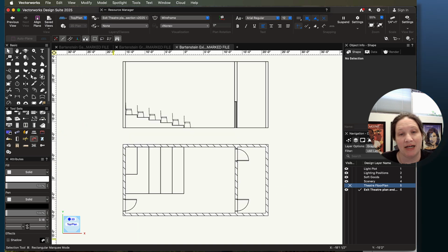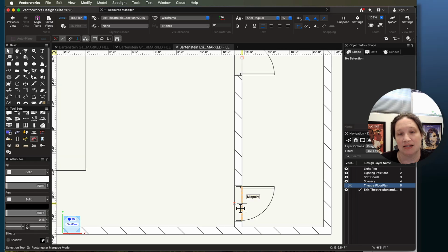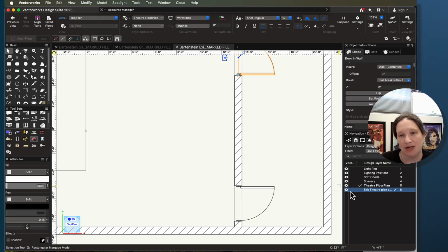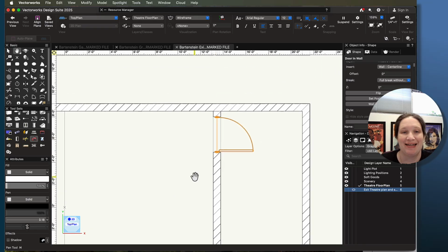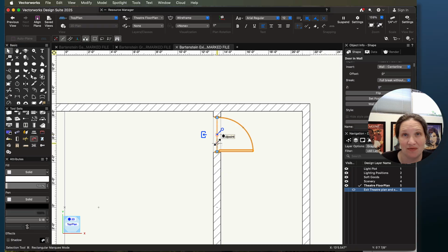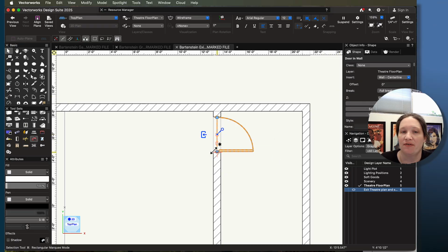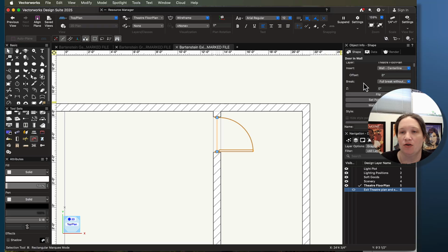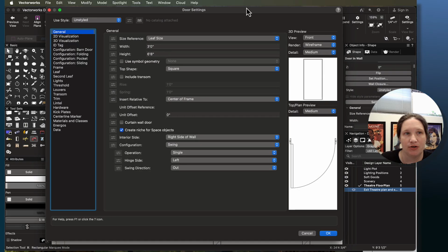In a plated version of this, you would actually not want to see solid lines here. You would want to see dashed lines. So we're going to do that in our floor plan, even though it's not the case in our tracing. So in order to get that, we have to actually edit one of the settings inside the door. So if you come into your door, you have it selected, you can come in over here and change settings, and it'll open up this whole door parameters box.